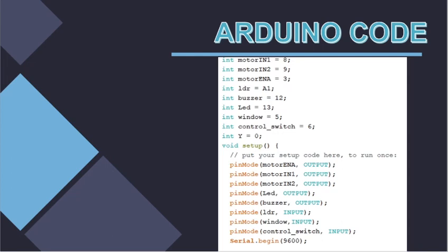Assalamu alaikum. I am roll number 2021161138, Lieutenant Nahinun Nabi. Now, I will be discussing the Arduino code which is used for our project. Here we can see the three inputs of the motor driver, that is input 1, 2 and enable pin, have been connected with pins 8, 9 and 3 of the Arduino.